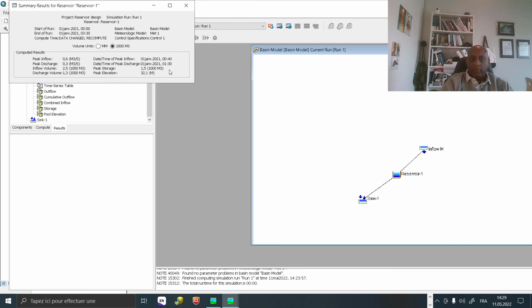And because we know the peak discharge, we can also calculate the length of the weir, the sluice, the gates. Everything, the gate must be designed to accommodate the discharge. So that is the advantage of hydrology, and that's all the information we need.